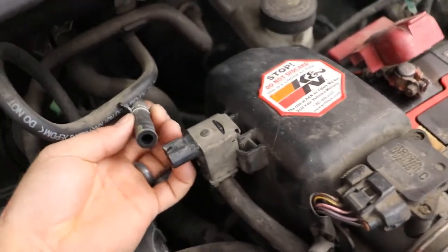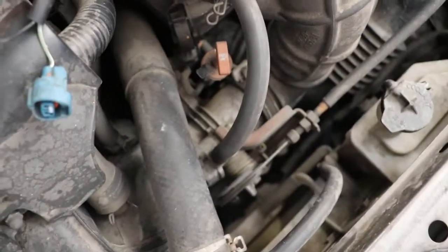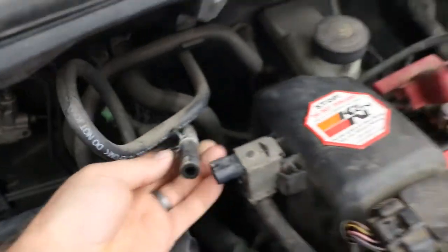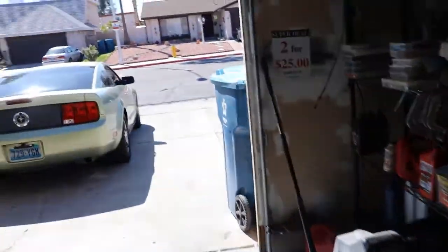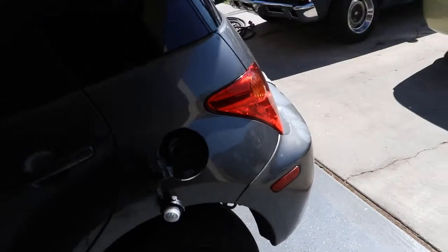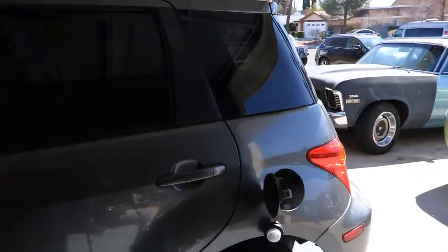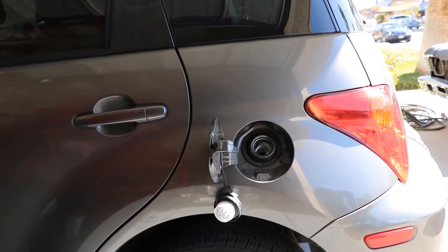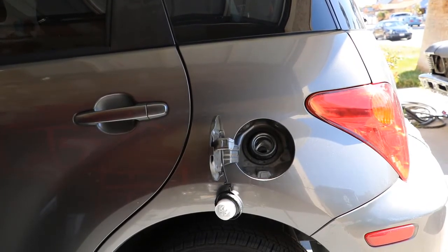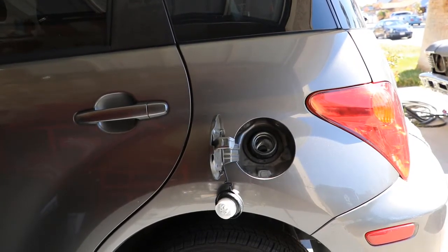So this is the purge valve. We already did this hose front part, and now this goes back to the gas tank. So I'm going to stick the tip of my air hose nozzle into that and give it a light pressure, very light, just because you don't want to damage any of the systems here. And I did open the gas cap already on the vehicle. Alright, so I'm going to try to flush some air through the system here. And so you should hear bubbles, you should hear sound. And I will also keep an ear open for it. So let's go ahead and try it here.